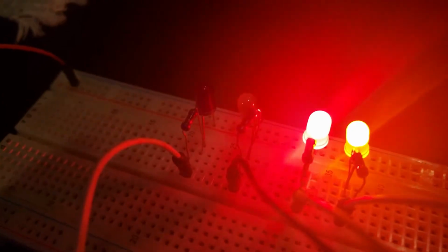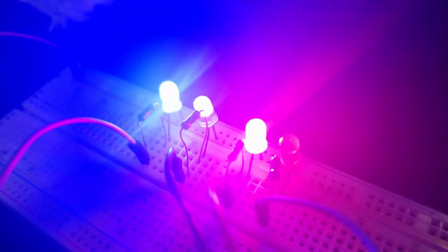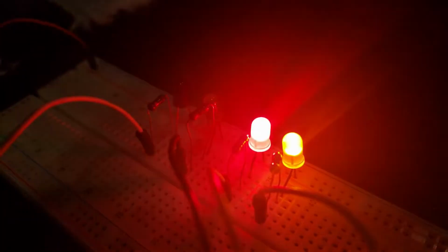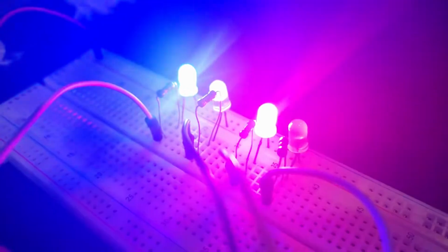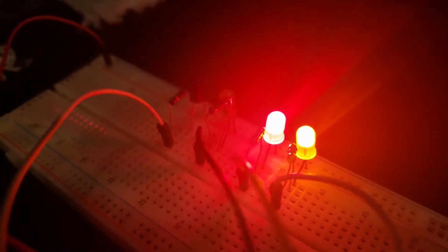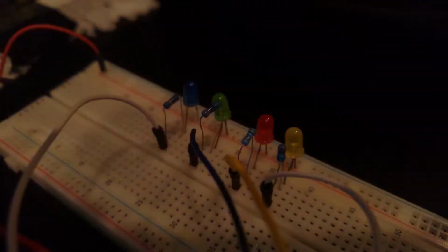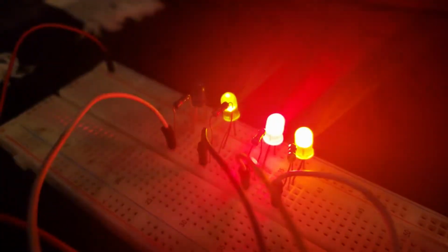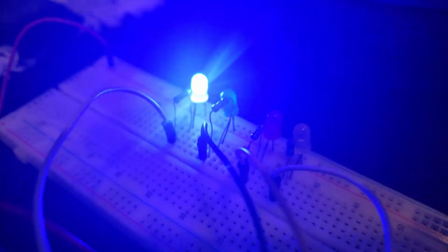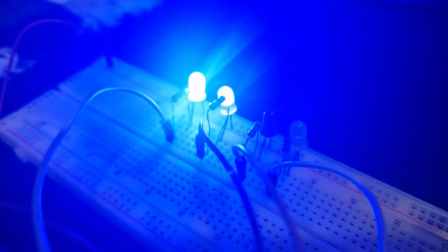It's going in, the wires are coming out, then it's going through these resistors, dropping the actual voltage for the LEDs, and as you can see, the electricity is flowing. It's manipulated to technically flow based on the code. So basically power is just going through each one in a certain amount of seconds, which is that 100 delay time, that 100 milliseconds delay time that we put in. That's what's really giving it that gap in between to flow.